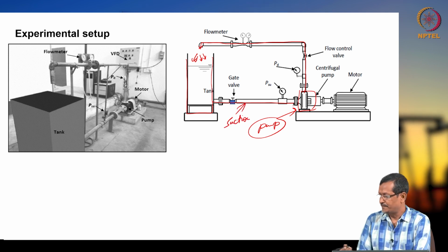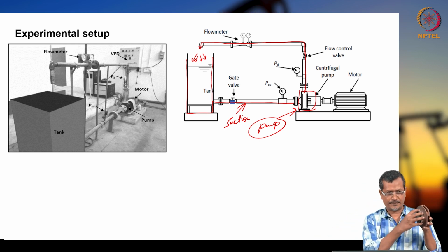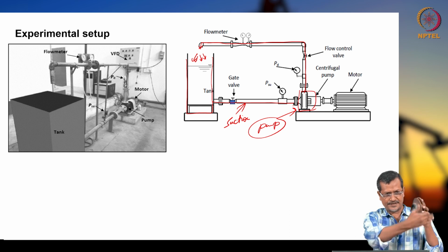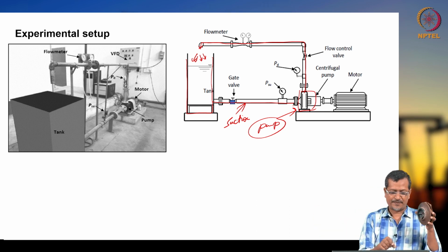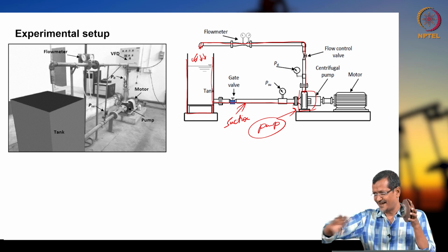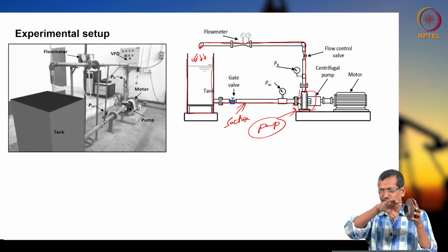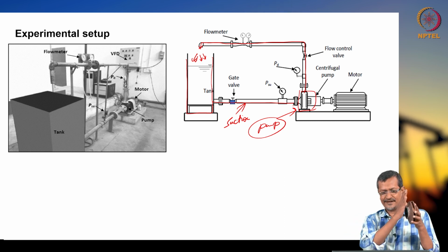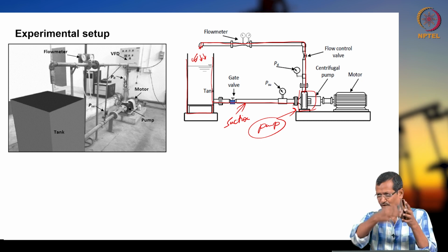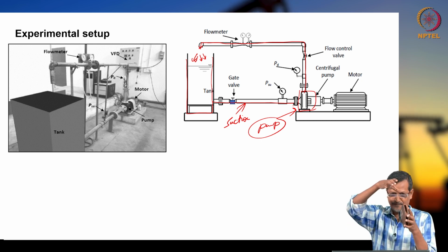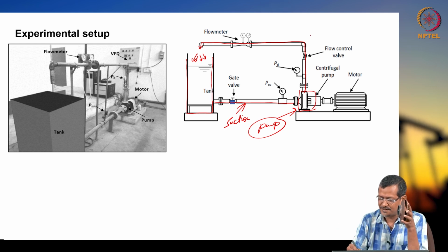So from the pump, I'll show this one. I said this one is the impeller eye. One casing is here, and from the casing one pipe will go to the tank or water supply section. From the water supply, fluid will enter, then it will be delivered. It will go out of this impeller, the volute will be there, then the diffuser will be there, and the diffuser will deliver to the delivery pipe. So where is my delivery pipe? This is my delivery pipe, you see this part.